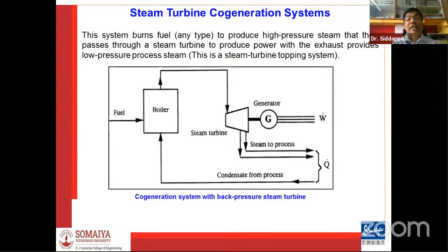And then the steam at a high pressure or the exhaust pressure generally depends upon the point from which you tap or bleed the steam from the turbine. If you are tapping at high pressure, you are going to get more enthalpy as well as more pressure, or good quality steam, but you have to justify it.